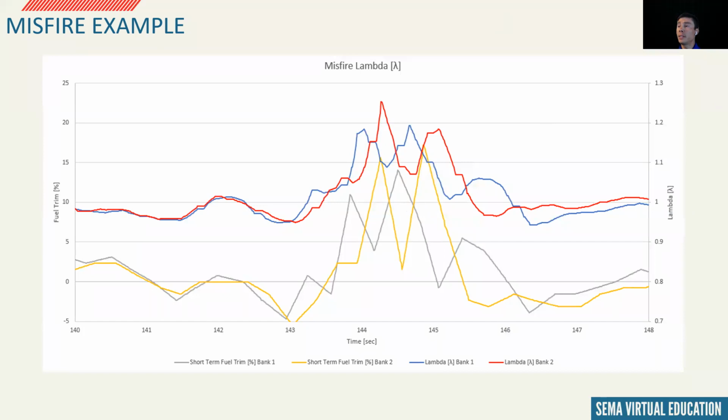Be careful of this during the nonlinear range of the injector. A nonlinear range can be thought of as the range you will see the most injector to injector deviation. This will happen at lower pulse widths, for example, under 1 millisecond.